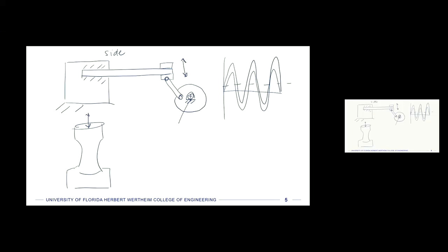So the one that we're going to use as a reference is the SN diagram, which I hinted at before. That's from that RR Moore bending rotating test, and it's used to create a set of failure points on many different samples.